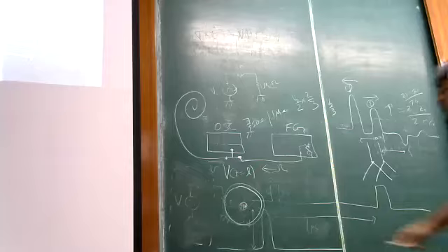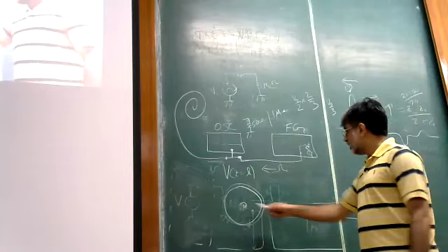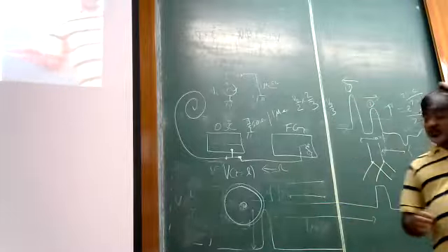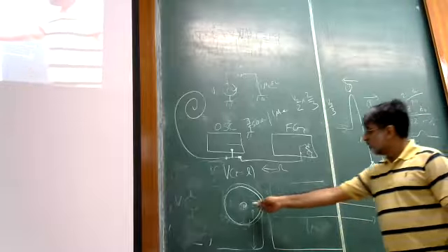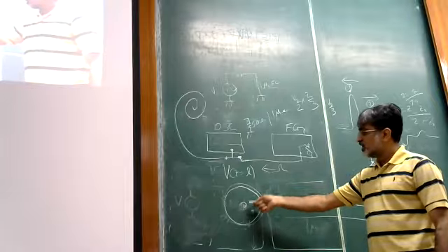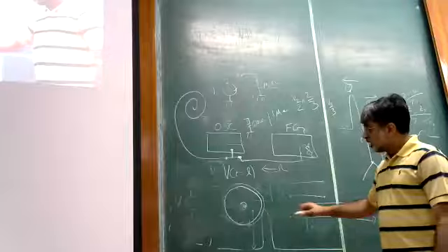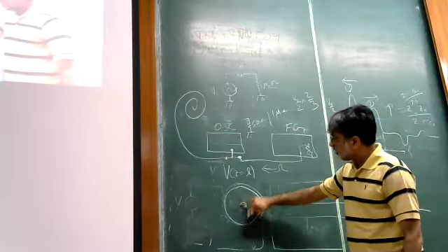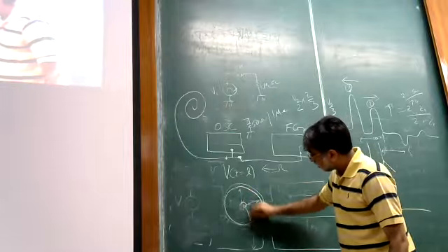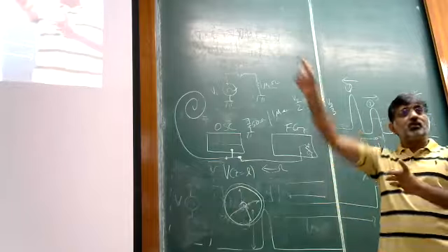Okay. So this, of course, is a cross-sectional view of the transmission line. If I just draw them like two parallel lines like we were drawing earlier, then one of them is the center conductor. So you have voltage of the center conductor with respect to the outer conductor at any point. And then the currents are flowing through this. Which means that here, because there is a voltage difference between here and here, electric fields are radial, right? We have voltage difference. So electric field is radial along that direction.